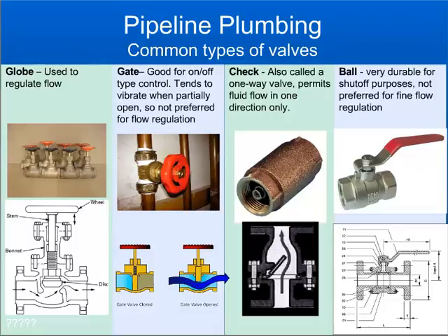Those are really designed and used to regulate flow. So they're good for limiting the amount of flow. They allow for a lot of fine-tuning of the amount of flow that you're going to get through a tap stand. And so that's why globe valves are recommended if you're trying to reduce that dynamic pressure as it's flowing through the globe valve and then ultimately onto your tap stand.